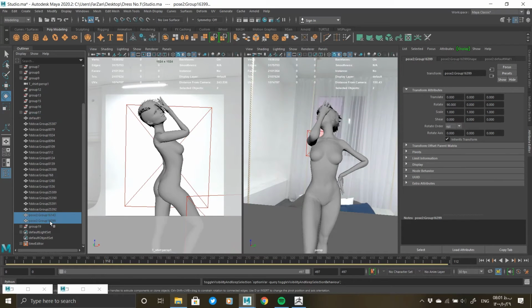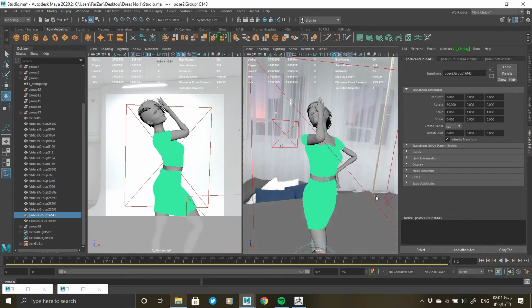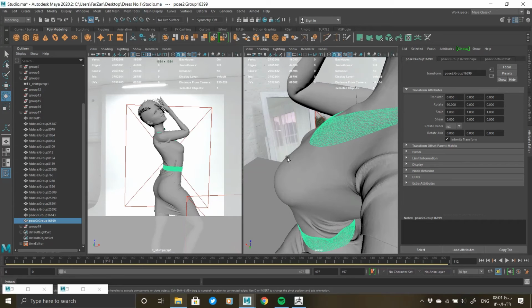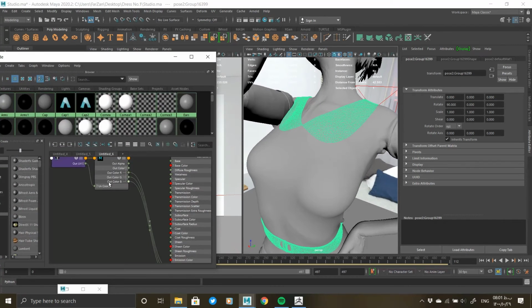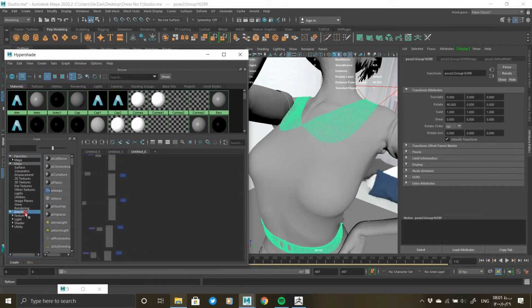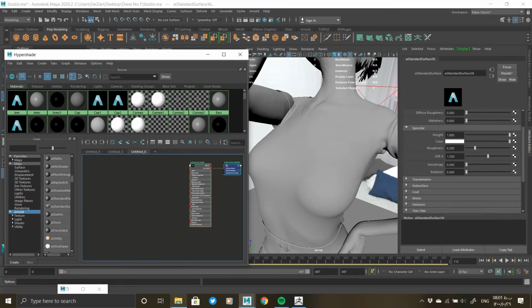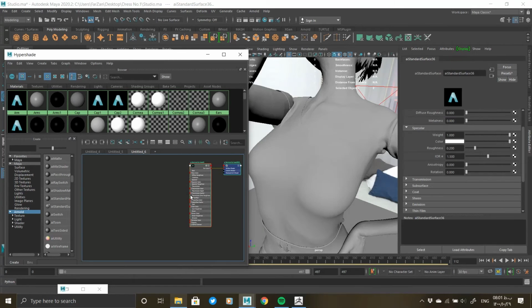We enter Maya and enter the low poly model into the studio. And after placing the camera and adjusting the lights, we start importing textures, and in the hyper shader, by creating an aiStandard surface, we start connecting textures to each of our parts. Different nodes may be used, including BUMP2D, displacement shader, divide. Then we attribute the made material to the model. We start testing the renderings, and in case of any problem in the light or material, we go to the relevant section and correct it to reach the desired light or material.